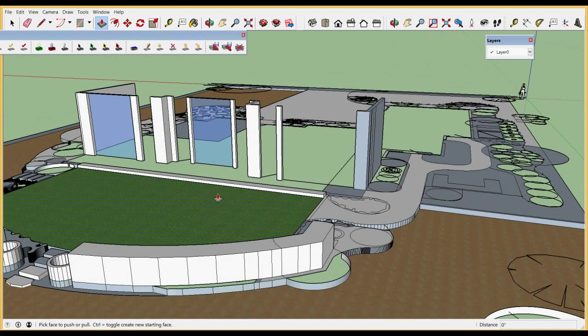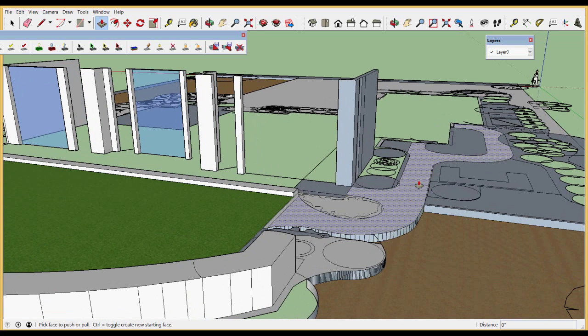Well, here is the SketchUp model being developed, just using that DXF file as a base and then applying textures, surfaces, pulling and pushing up as required. For example, we've got a complex path running through here. You can see how easy it is to select it. This zone through here might well become a clump of perennials, so we can just bring it up like so, and then we'll apply a pattern to it later.